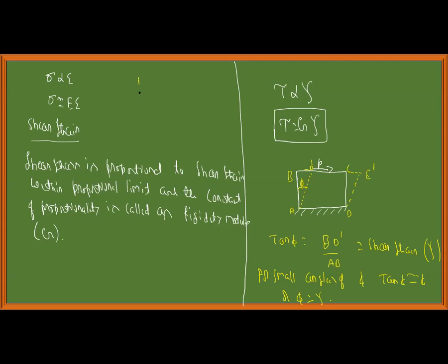When you take a bar like this, and if you apply a load P like this, the increase in length was the deformation. Delta L is equal to PL by AE. It is nothing but increase in X dimension or Y dimension or Z dimension. Change in length or width or thickness is your deformation. Whereas if you take the ratio, epsilon is equal to delta L by L, that is your strain.